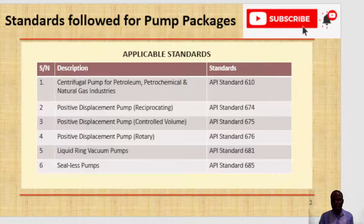And then API standard 675, which is for control volume pumps, another classification of positive displacement pump. We also have API 676 for rotary pumps, which are also positive displacement pumps. And then we have API standard 681 for liquid ring vacuum pumps. And then we have API 685 for sealless pumps. So these are the applicable standards for other pump packages.